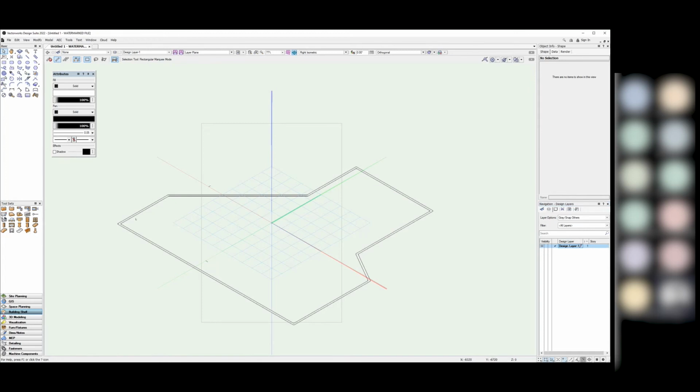Let's say this is a full-blown building. Let's say we're doing the Jeffrey Manton building. We've got loads of external walls. We've got a mixture of internal ones, might have some partitions, might have some glazing and things. If all of that is defined by the layer, rather than me just typing in numbers, it means that if I decided I want an extra 500 millimeters of height, I could just edit the layer and everything will update.